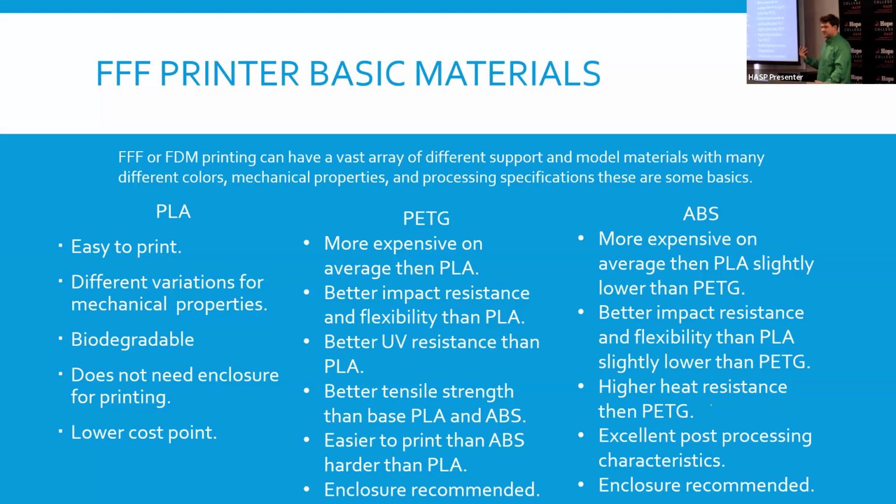And then there's also a trick with some acetone, where you just take acetone, it'll break down the ABS and create a smooth surface finish. So instead of having layers like this, you can take acetone, wipe it on quickly, wipe it off quickly, and it'll create a smooth surface finish to it because it breaks down the top of those layers.